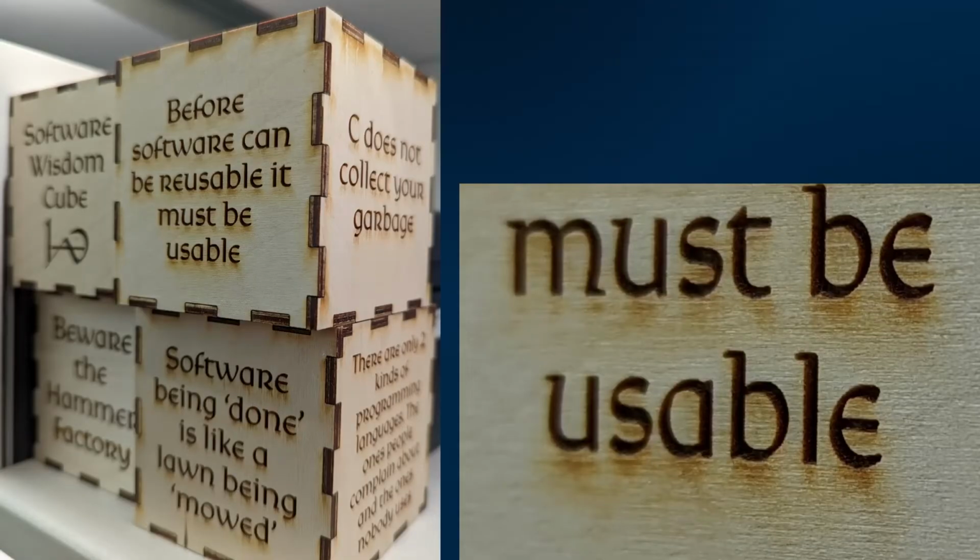All right, so here is something that is super common for people to do with a laser cutter. In fact, at MomoCon in the dealer's room, there were innumerable merchants selling something like this. So here we have a box, and this box is combined using finger joints. So what you have are 6 individual panels cut off the laser cutter that you basically push together. Again, the tolerances on here are really, really tight, so with a few light mallet taps, you can put this together.